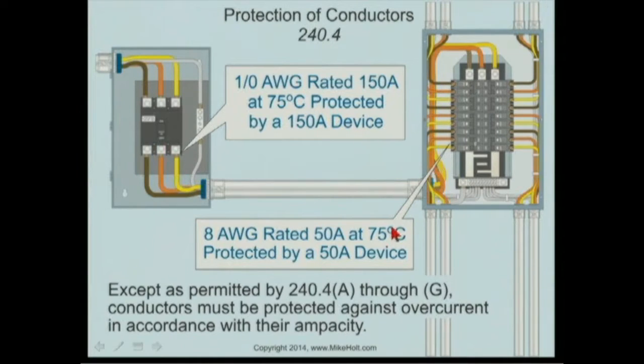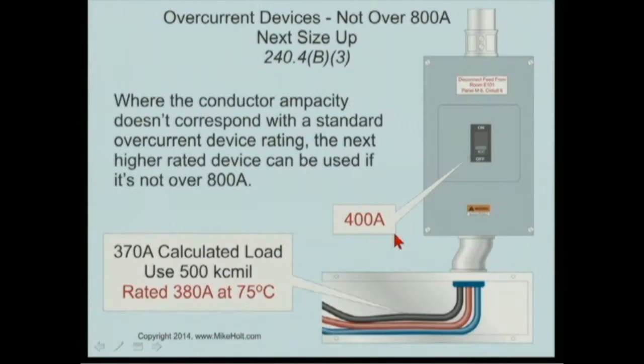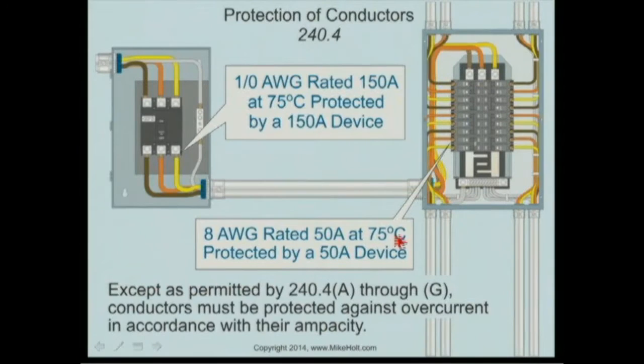Let's go over here. I have a 50 amp breaker here. It looks like a 2-pole 50 amp breaker. I'm running 8 gauge wire. I go to table 310.15(B)(16) at the 75 degrees C, only assuming the terminals are rated for 75 degrees C.